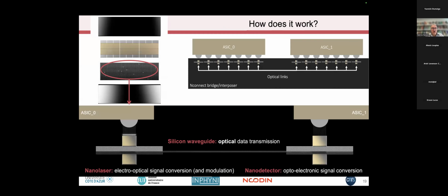And basically how it works is the chiplets are packaged with little bumps under them. And what you will do is stick these bumps directly onto the lasers and photodetectors in order to provide links at the millimeter scale, centimeter scale that is needed on the chip.